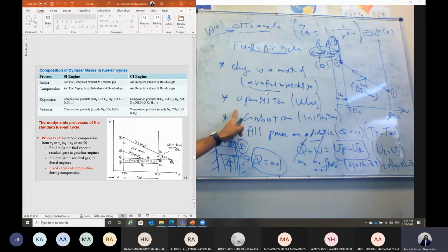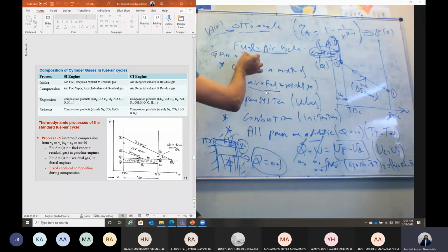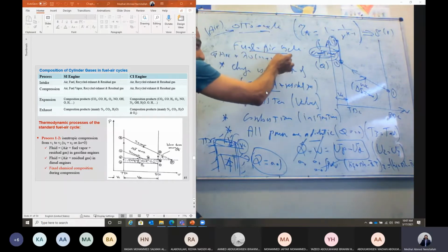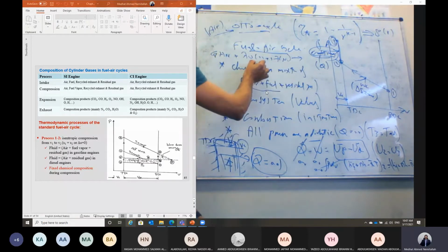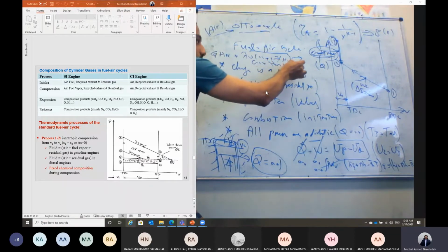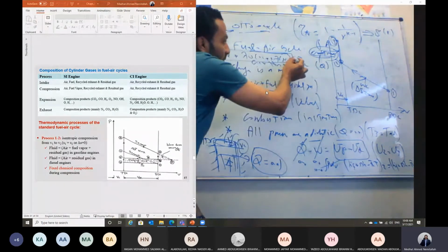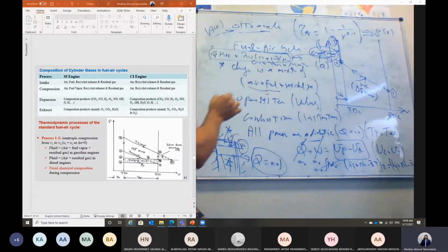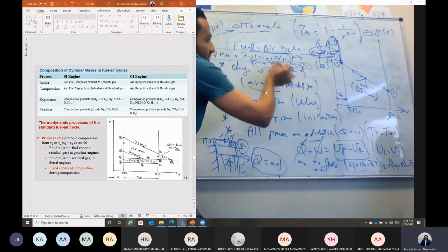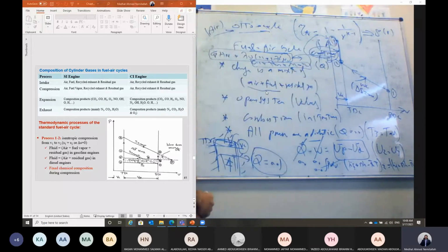That means in this cycle I have to write down the combustion equation. In this case, for any fuel, like let's say isooctane, C8H18, at a given equivalence ratio or excess air factor lambda, gamma O2 plus 3.76 N2, then we can have the products CO2 plus H2O plus N2 plus O2, all of this. So those are the reactants, which are at point number 2, and those are the products which should be at point number 3.